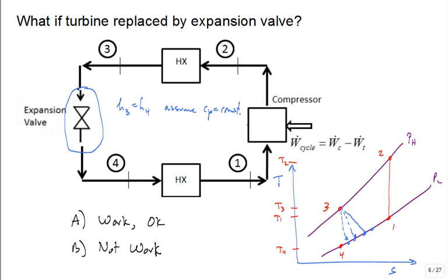Just make a list of all your properties. Start with P, T, V, U, H, S. True? We've studied these expansion valves. I know what the change in H is across that expansion valve. There isn't one. It's isenthalpic. I also say it's an ideal gas with constant specific heats. What other property is constant across that valve? Temperature. Do you see the little logic there? Temperatures. Okay.